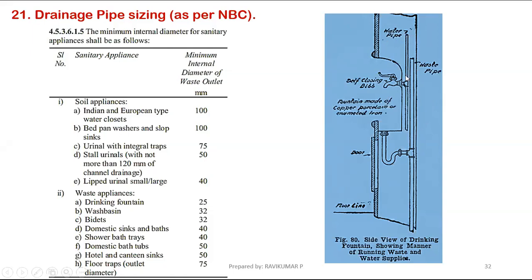This is the water inlet. For the outlet of water, we have to provide one drip tap. This is only the standard size; we have to keep that in mind. From the outlet, how we have to connect the header, the header size and the branch pipe size, they have provided in a tabulation. You will see it in the next slide.